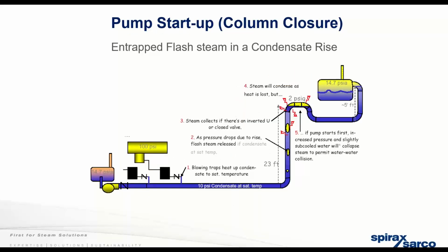Next one's kind of interesting. What we're showing is a typical large-scale piping system, possibly in a hospital or a university where this is common, where we're discharging steam traps and pump condensate into the same line. So as long as our piping's good and we don't have any pockets where flash steam can form, we shouldn't get any slug flow, but we may get pipe bubble collapse.